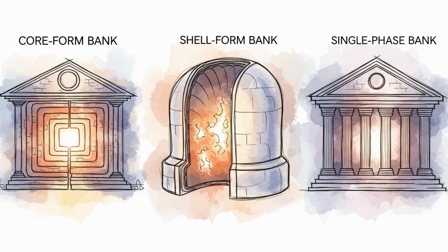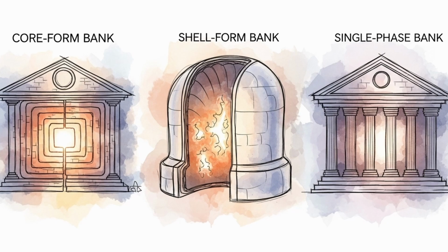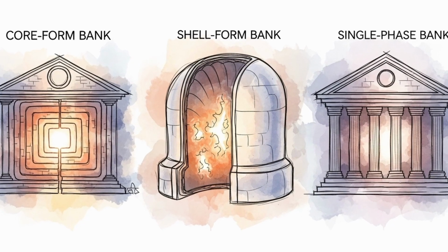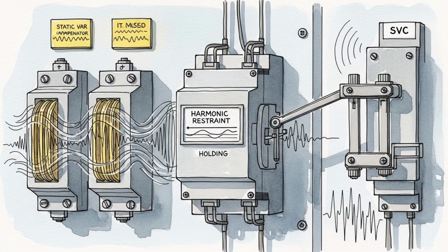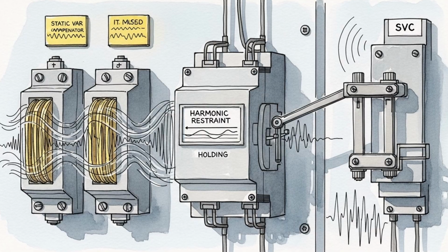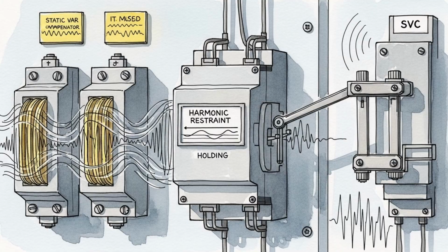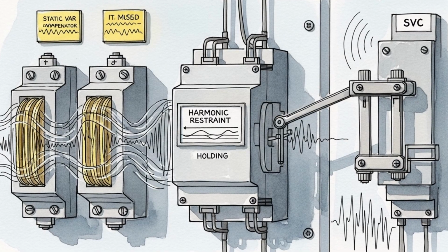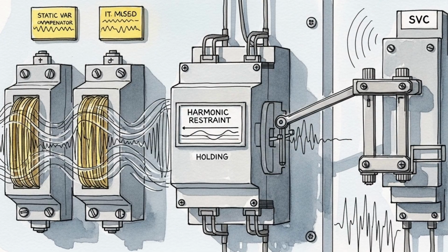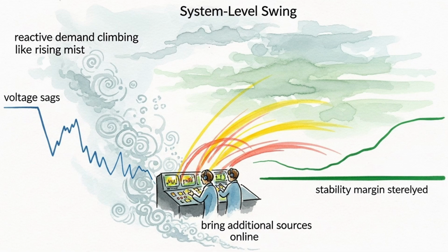Local geology sets how the induced electric field maps into actual currents. Rocks and soils differ in conductivity. Sedimentary basins and coastal regions with conductive seawater can support larger induced fields over wide areas. Shield rock with low conductivity can focus gradients along boundaries. The same external disturbance can therefore produce very different currents in two regions with different geology. Regional risk maps are built from conductivity models and past measurements.